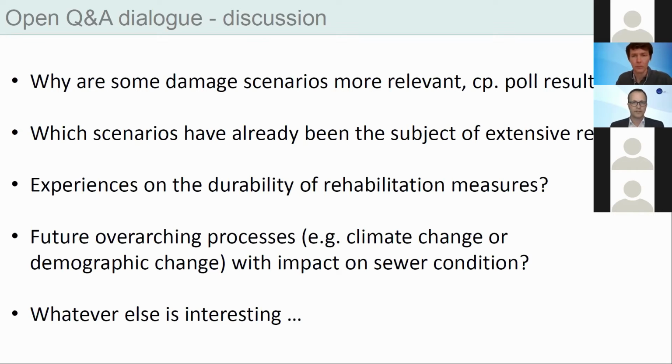Well, the origin of this MAX system, where we push from the inside and measure the deformation, was, as I said, in Paris. And so it started with large diameters. That's also the main area of application. So large concrete, steel reinforced concrete pipes, or masonry, where it's very interesting to see how stable a masonry sewer is in a pipe-soil system. So that is the main application area. And you can check any material with this method.